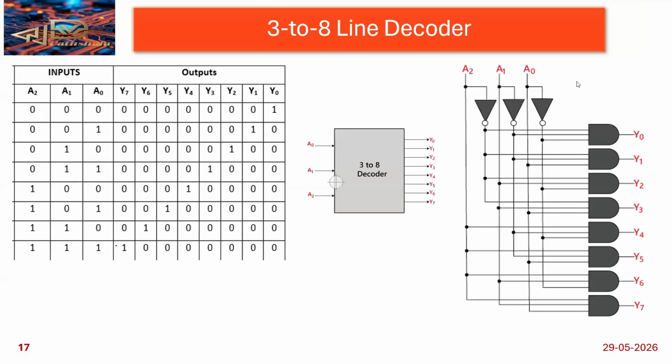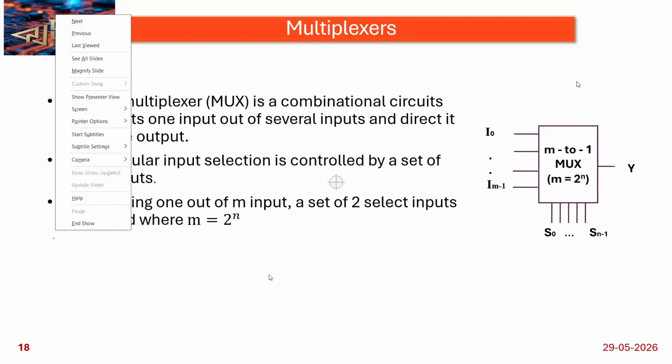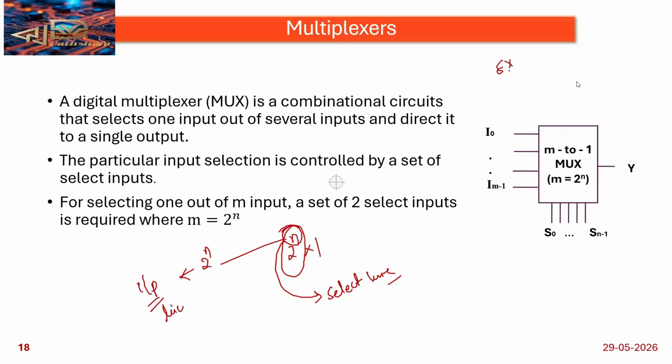Okay, this is the multiplexer. We are giving multiple inputs but a single output. See, a multiplexer has inputs as well as select lines. Here in 2 power n by 1, this n defines the select lines, and this 2 power n defines the input lines. Suppose you are designing an 8 by 1 mux, I write this 8 as 2 power 3 by 1. This 2 power 3 means 8, right? 8 inputs I am having. How many select lines are there? This 3. 3 select lines I am having. In this way we will design the multiplexer.